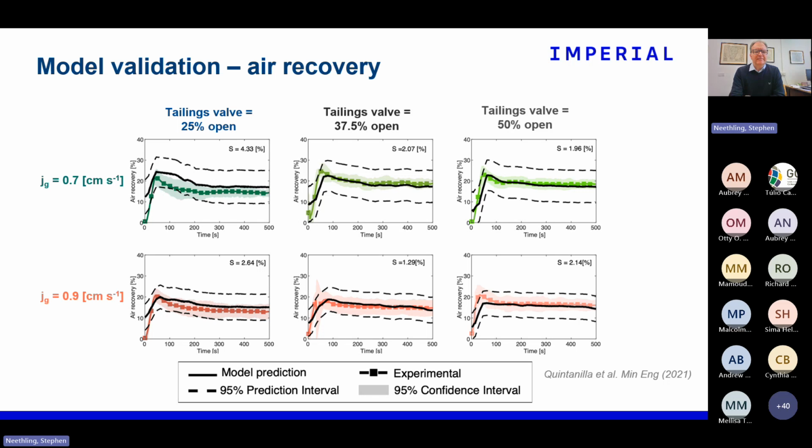The thing, though, with these models is if we're going to use them for control, particularly for feed-forward model-based control, we don't actually need to have our models be exact. These sorts of analytical expressions are actually very good, because the key factor, if you're going to use this sort of modeling in a control setting, is that it has to go in the correct direction.